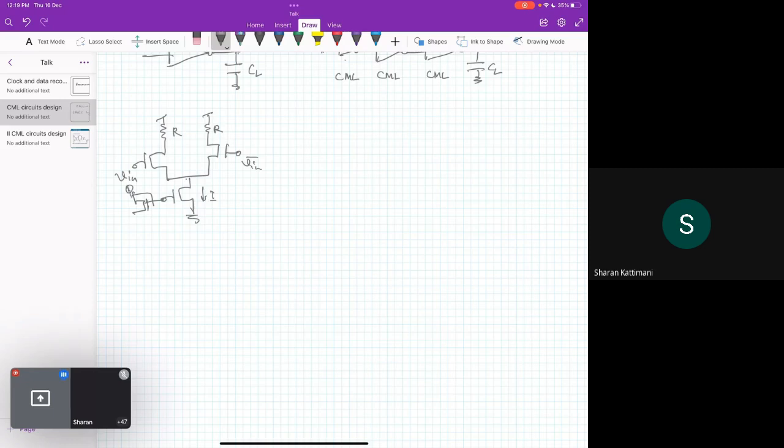Okay, so I am not showing this, but this is connected to a current mirror, and again similarly another differential architecture, but this time the current will be K times larger. That is why the W of these transistors will be K times larger, and the output of this logic will be connected to the input, and the output will be taken from here.